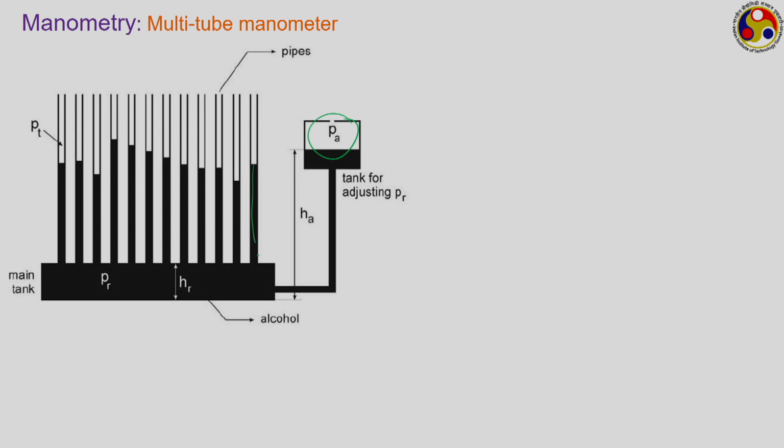We can visualize this particular one as one U tube manometer. Similarly, we can also consider this particular one as another U tube manometer. This way we have several U tube kind of manometers, or maybe well type manometers, coupled in the same device. This kind of configuration is called a multi-tube manometer. Quite frequently you will find the application of this in industries and even in laboratories also.